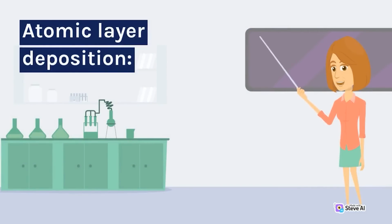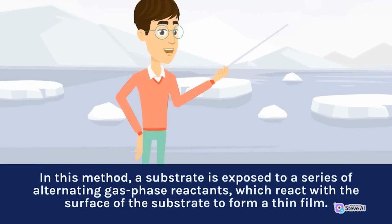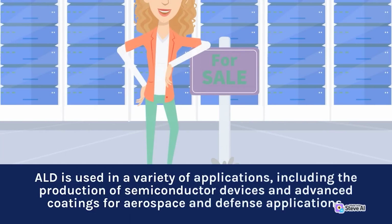Atomic layer deposition. Atomic layer deposition, ALD, is a process used to create a thin film of material on a substrate with precise control over the thickness and composition of the film. In this method, a substrate is exposed to a series of alternating gas phase reactants, which react with the surface of the substrate to form a thin film. ALD is used in a variety of applications, including the production of semiconductor devices and advanced coatings for aerospace and defense applications.